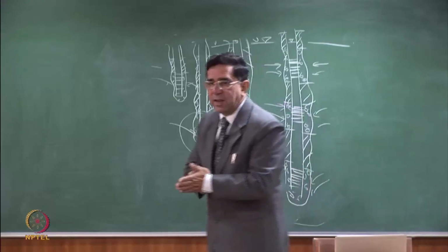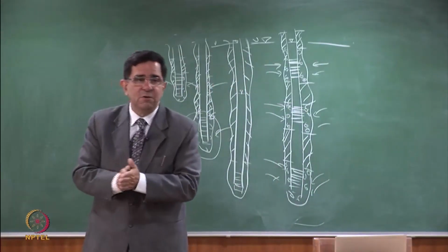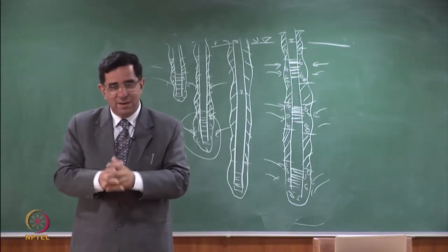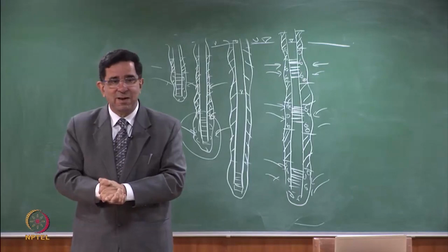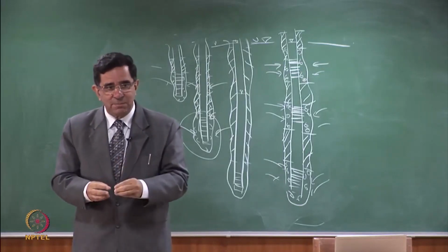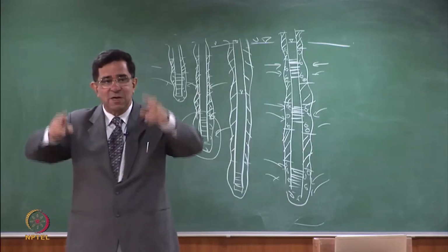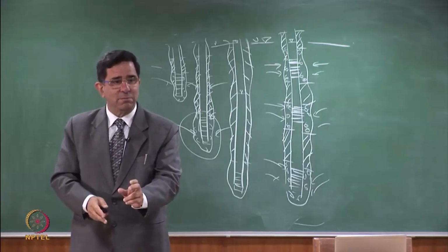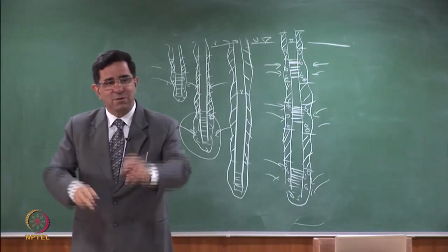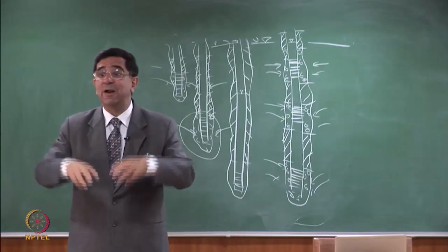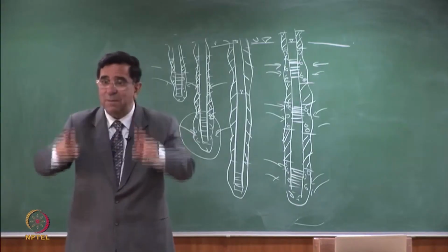So we'll stop here today, and all that I have introduced to you is how do you make a well, and how do you take a sample out of a well, and how a well will not give you a sample from a particular depth, it will give you a sample which represents the entire zone in which the filter pack is there. Your screen may be at the bottom, but if the filter pack is there, typically in all wells where we are trying to get out drinking water, there will be a huge filter pack all around it.